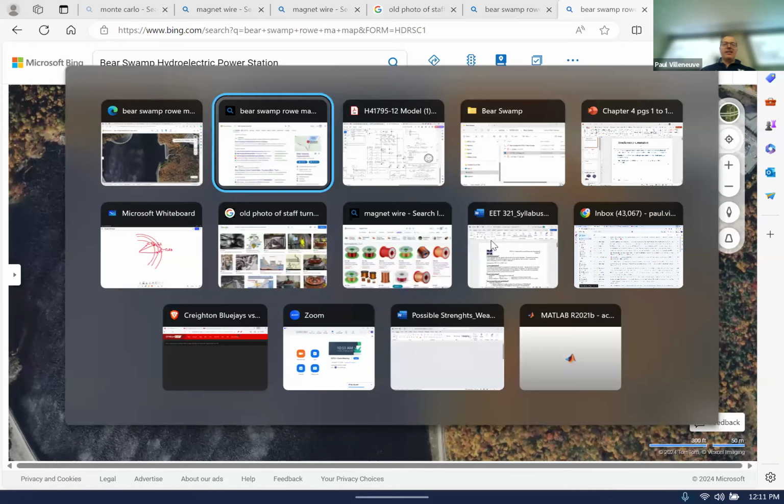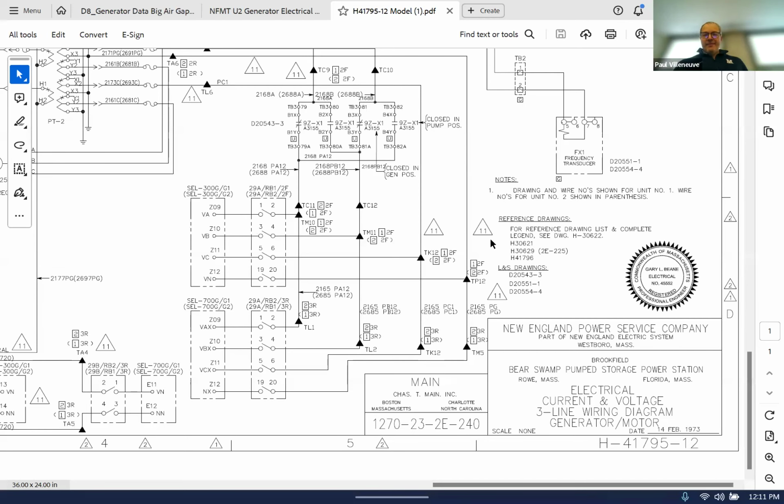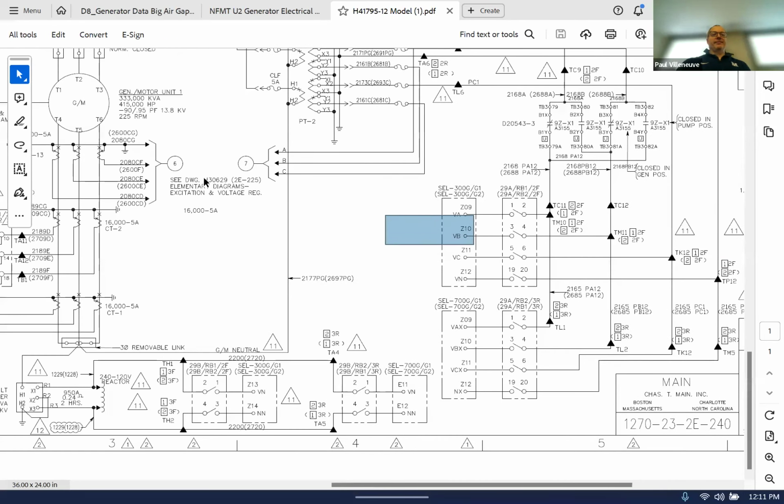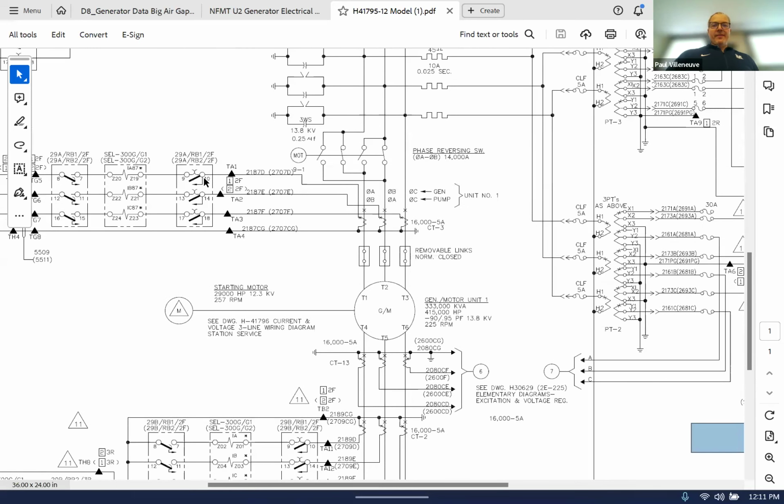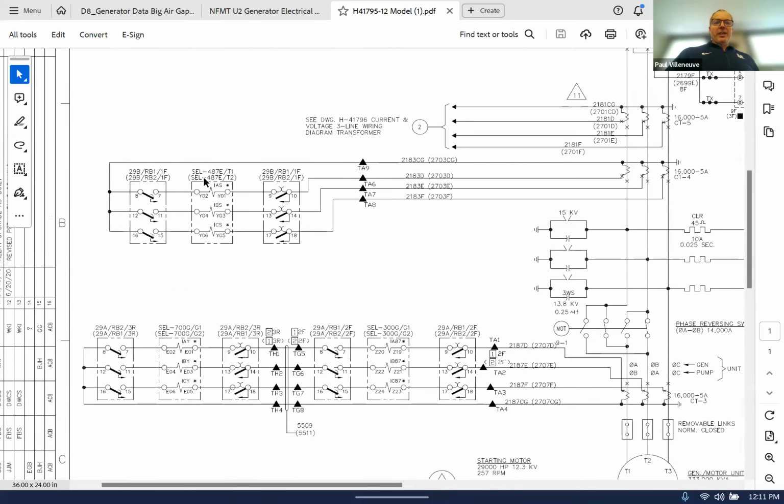And that's an AC elementary or a 3-line diagram. They call it 3-line, but now people are calling it AC elementaries because it's elementary, right? It's the basic. That's where the term comes from. And it's AC because it's the alternating current basic drawing. This is literally how you wire up the AC part. Not the DC. Sometimes you show DC in here, but this one you don't even see. It doesn't even show you the field winding.